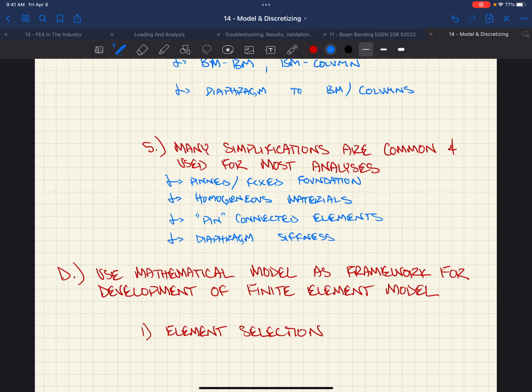You can go from one end, which is assuming that it's simply supported, right? And it's just based on tributary area. Then you start thinking about stiffness and load path and continuity of the system. Then you're saying, okay, well, does it really behave like one continuous beam, right? Is this pretty much an integral beam over a bunch of supports? Do we assume those supports are stiff enough that they stay restrained? Or do we start looking at the fact that this thing starts moving, and when it starts moving, then we get torsion?